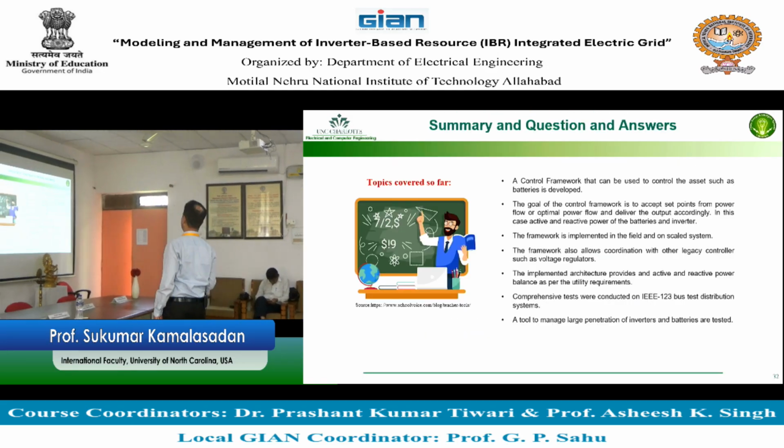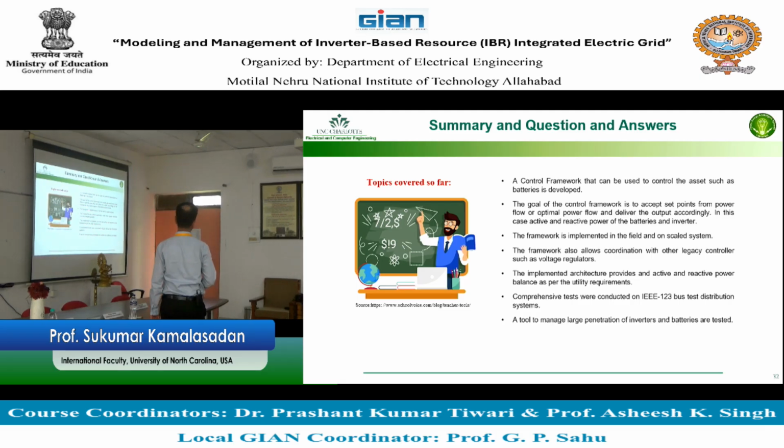Okay, so today we talked about the control framework and how it is implemented. We talked about how you do node voltage control with the legacy control part, and node voltage control with respect to time. Then we extended that to the relation of active power with node voltage control: how we do active power with voltage, which we call volt-watt, and volt-var. And finally, we looked at a tool that can be implemented to do groups of this in a power distribution system. So that is something we gained some knowledge on.